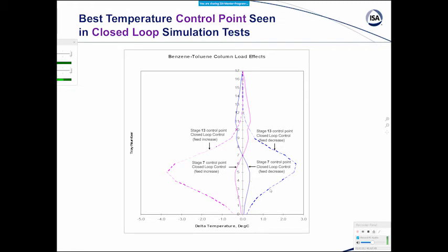control here. When we compare it to the dashed line, if we look at tray 13 and just look at it, not knowing what's happening on the other trays, we say, oh man, we're doing good. In fact, it might look better in terms of the nearby trays. You don't have much of an excursion. But look what happens as you go to the lower trays. The excursion is huge, really terrible.